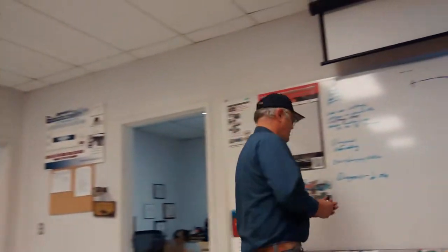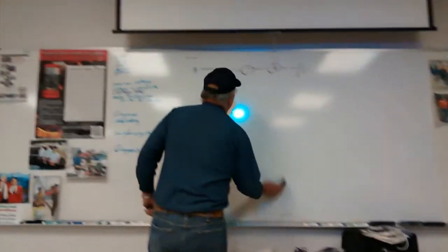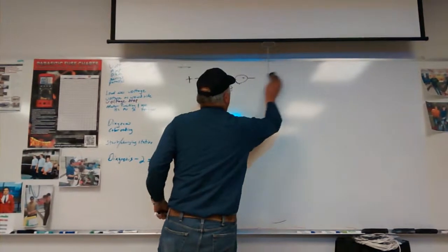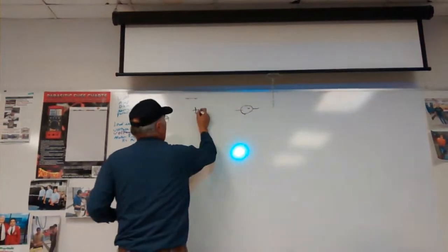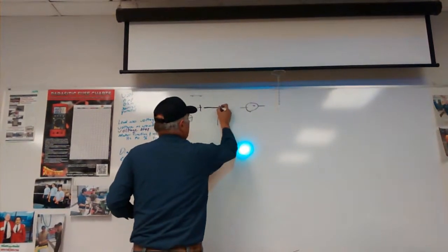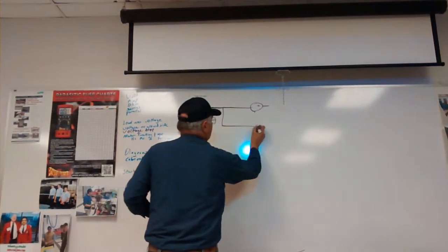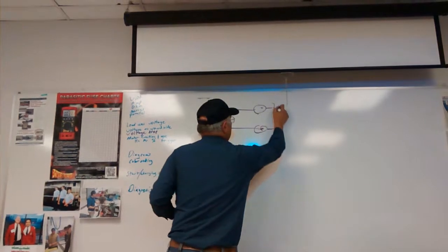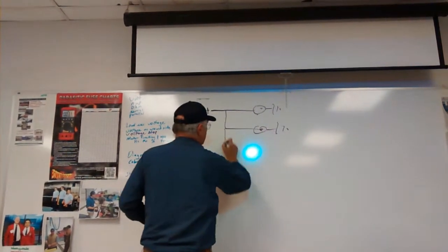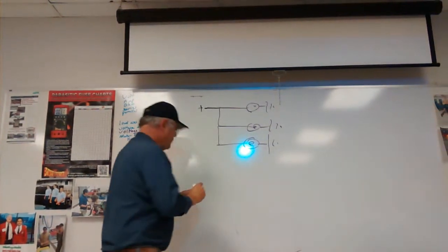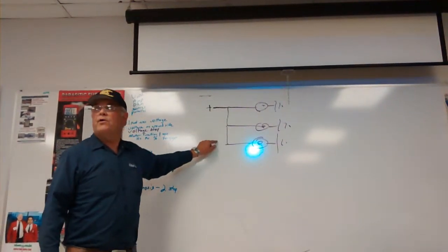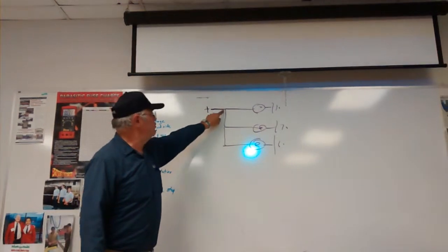All right? A parallel circuit means that we have one power source, and it comes and it may feed this one, and this one, and this one. An example for this would be lights on the cab of a truck. We have one 12-volt circuit.